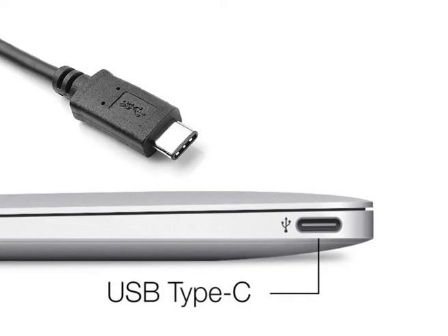In coming years, Type C USB is going to be very popular and commonly used. Developed at roughly the same time as the USB 3.1 specification, but distinct from it, Type C specification 1.0 defines a small reversible plug connector for USB devices. It is common both for host and the devices and meant to be future proof. It has a 24 pin double sided connector similar to micro B connector and of size 8.4 mm by 2.6 mm,